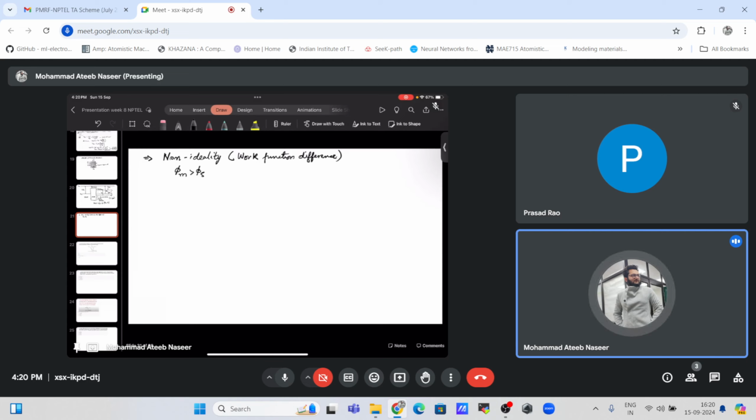So what would happen at the interface is that the oxide semiconductor interface will now be depleted of the electrons, and there will be accumulation of the holes, because the surface has got some reduction in the electron concentration because of the equilibration process that has happened.